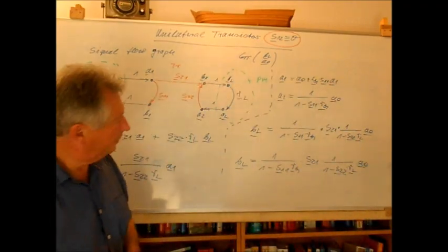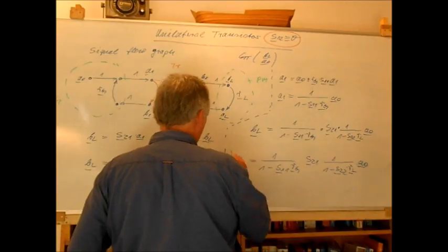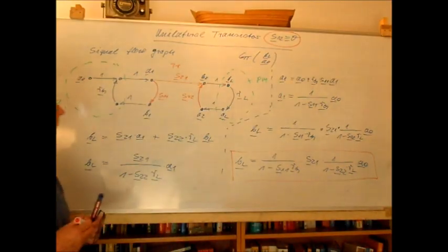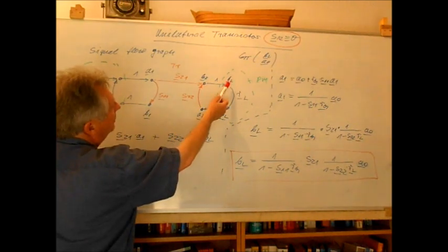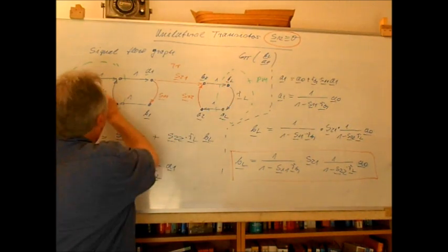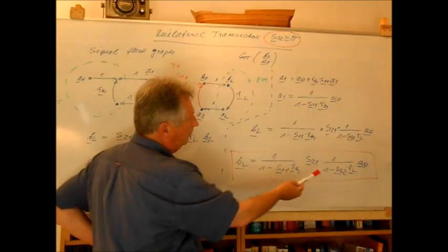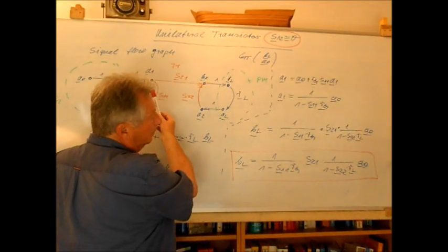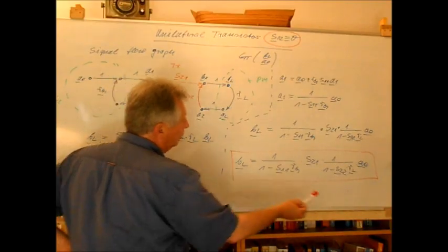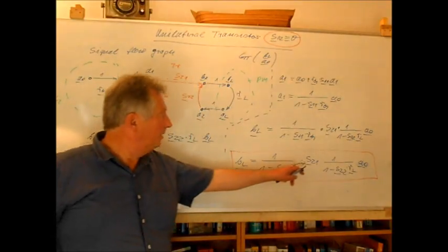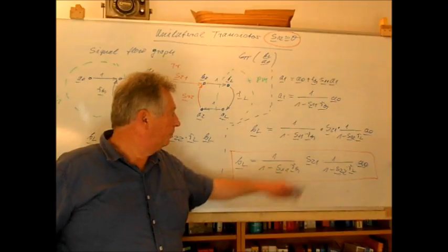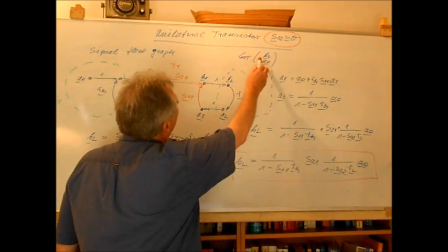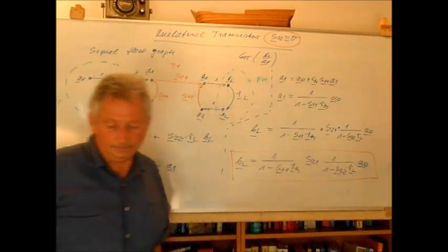So what we have here is now the wave amplitude inside the load, independent of our wave amplitude, which is generated by our signal generator, and in between the generator and our load we have as an active device an arbitrary transistor, which is described by its S-parameters, and this we can insert into this equation.